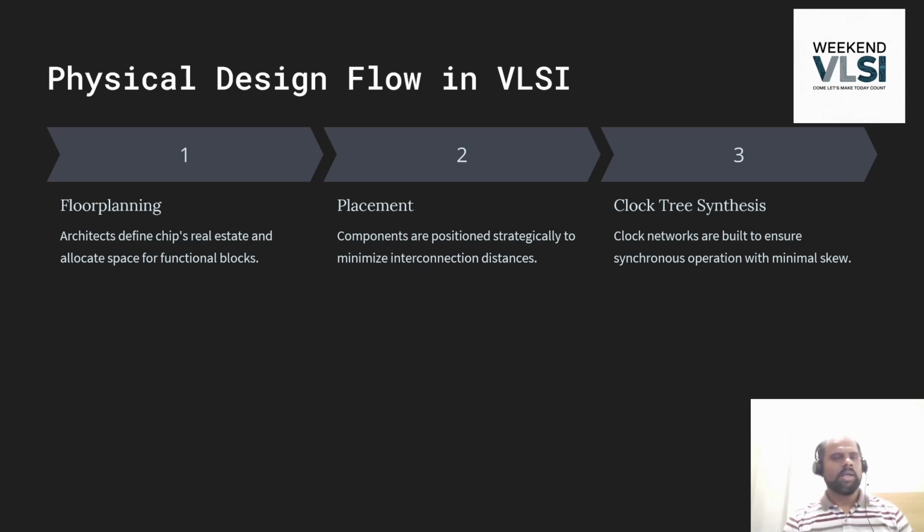Okay. And one more important step in this process is clock routing. Okay, this is the place where these clock paths are routed. Before that, all we do is with either virtual routes or global routes. These are estimations. Now it is the actual route which is getting put in place.